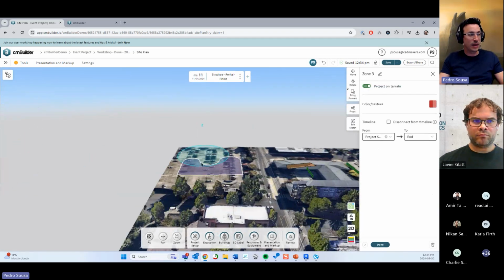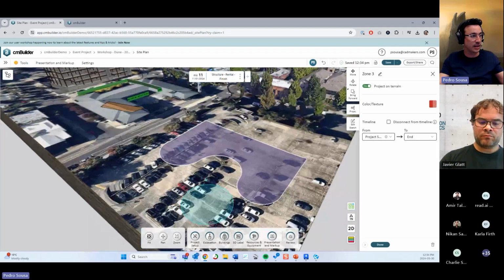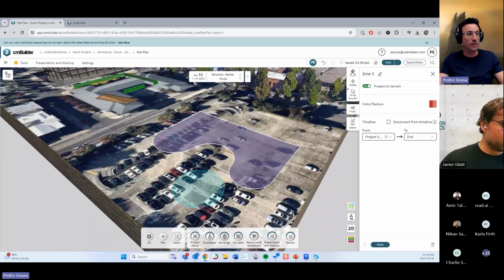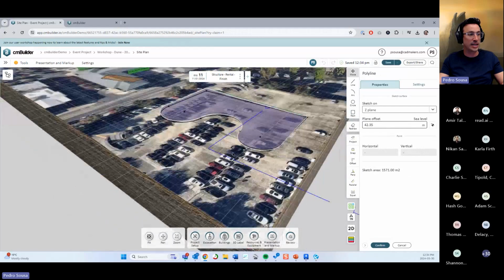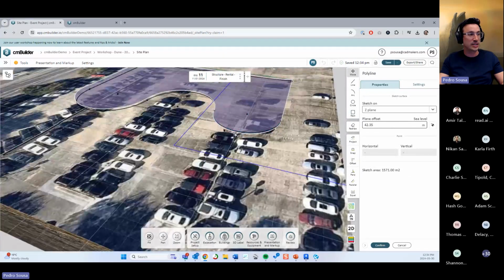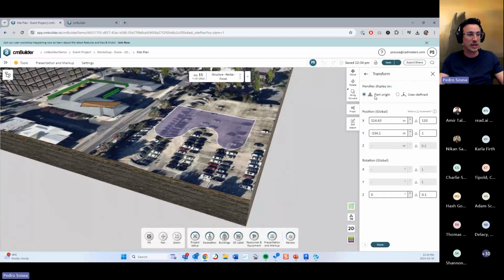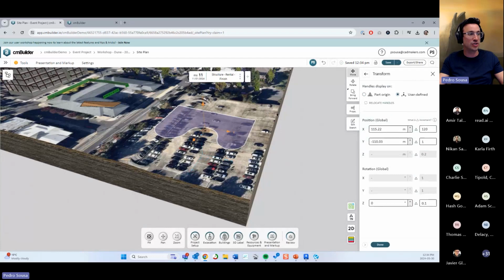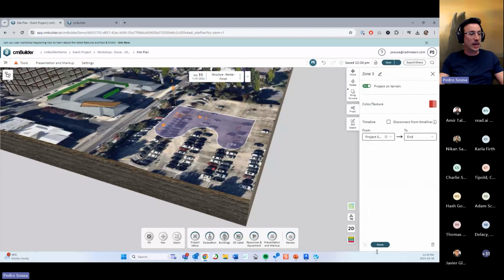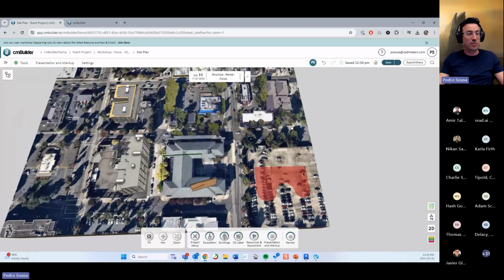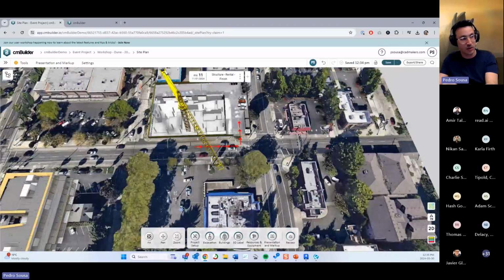For linear objects like the zones, lines, and linear objects like fences and so on, the part origin will always be the same origin as the origin of your sketch. So this center point over here of the V and H lines is where your part origin is. But of course, you can change this with user define and place it wherever you want by double clicking on that object. This is super useful whenever you're placing a drawing, for example, and you want to zoom in on a location to align the drawing according to that location specifically.